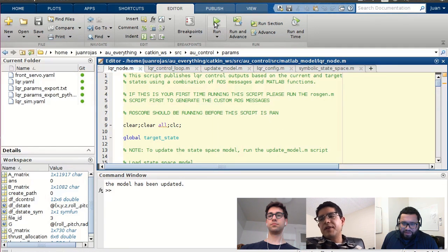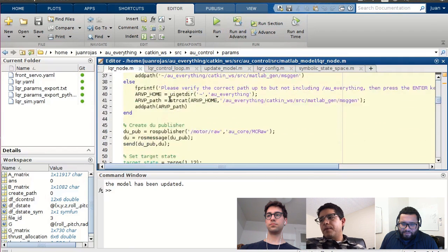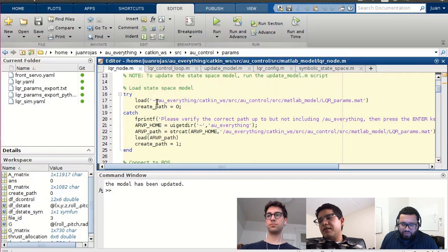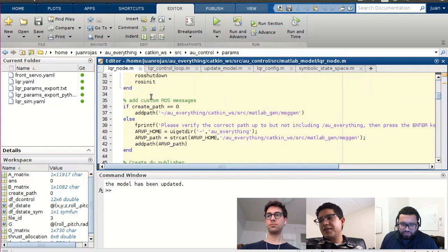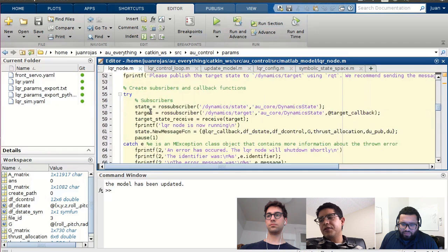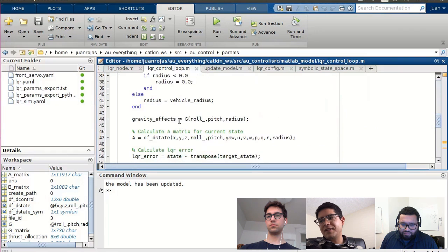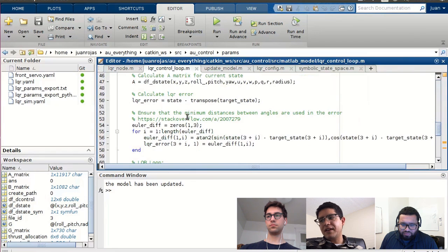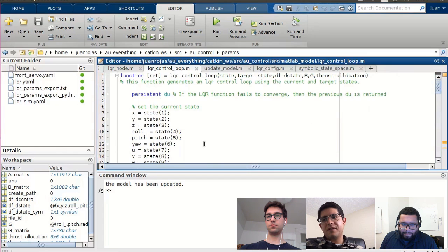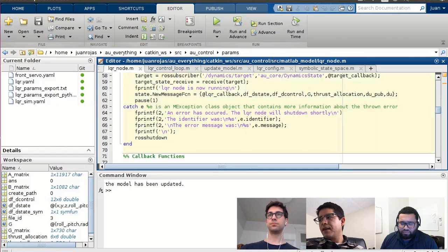Okay. And then the reason we moved it to Python was just so that we could run it untethered with the robot. That's what works with your entire system. Yeah, just because of our hardware constraints. Correct. So basically, what this file does is it'll connect to the ROS master, and then it'll run a control loop. The control loop basically calls the LQR function, and then it'll input whatever state it gets from the sensors, and in this case it'll get the state from our simulator.